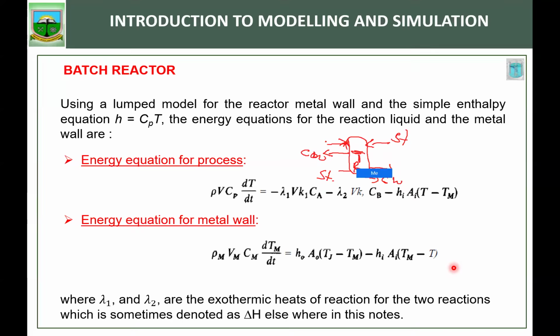So we now have to account for all the energy terms. The first energy term, because it's a batch reactor, we are not flowing the reactants in, so we can't talk about that one. The reactor is not flowing in at a certain temperature, so that one does not really have a problem. So the accumulation of energy or temperature in this will be what? Delta MH, you remember, dt, where this is enthalpy, right?